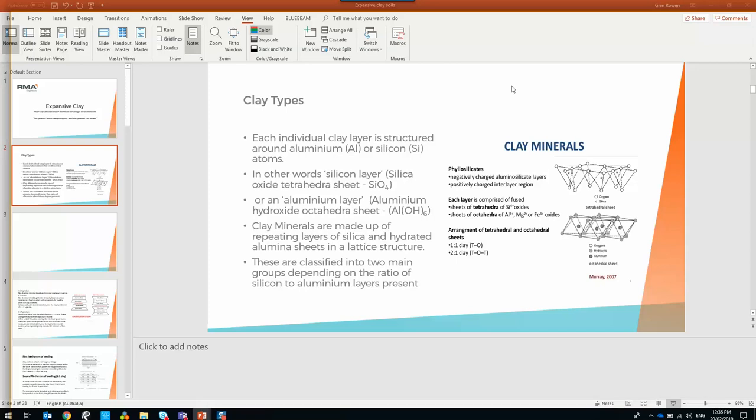Then you get a site classification, which is, I don't know if you're all familiar with that, just a table out of AS 2870, the residential footing code. A lot of soil reports you get for commercial work won't reference that, but it is a good guide. So basically, A down to H1, nothing much to see here. It's easy to design against them. It's the H2 and E footings that we're focusing on today.